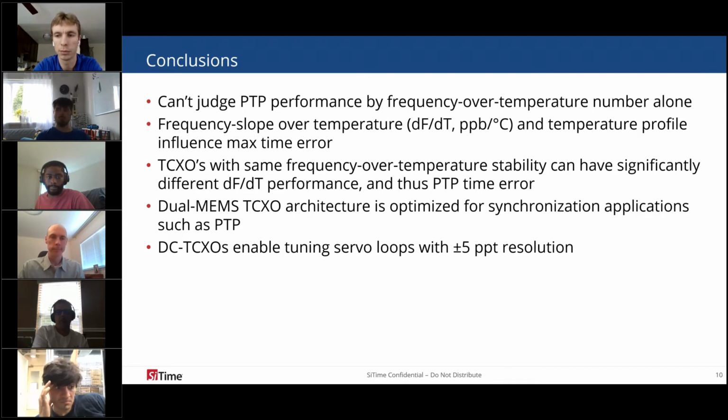And what I would recommend is when you're evaluating a new oscillator, just blast it with heat, with a hair dryer or a heat gun, warm up the board quickly, see what it does in those conditions, and then you will have a better intuitive understanding of whether conditions in your design will be acceptable for this device or not.